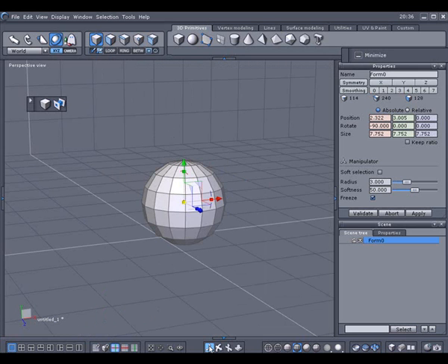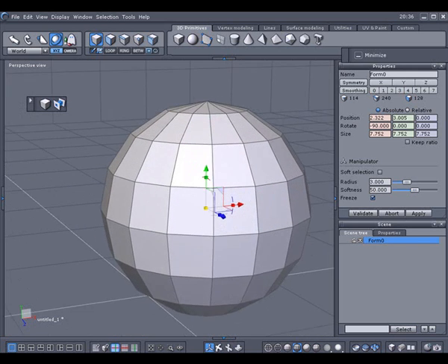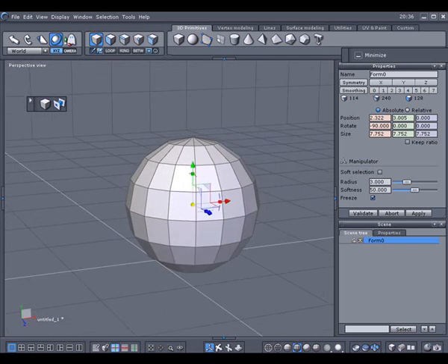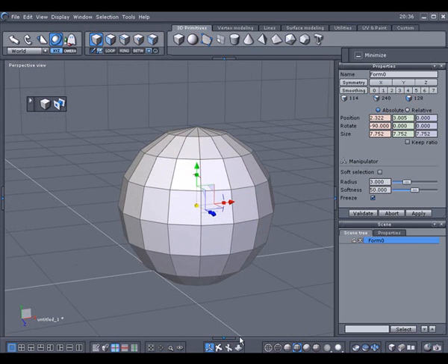Alright, we're going to go over a little bit of these navigation icons down here, and I got a list of them where they rotate, pan, and zoom, and I'll show you this first one here in a second. When I select this icon here, you can hold your left mouse button down on the icon itself and drag your mouse in and out, or up and down.